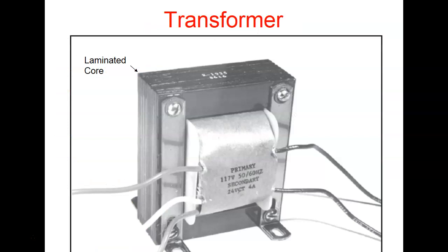So this is a transformer. In most electronic transformers, industrial transformers, especially small ones, the actual wires are going to be inside some type of plastic enclosure. I showed y'all magnetic wire last class, right? Very, very thin insulation. And if you accidentally nick that stuff, then what would happen? Now you're going to short out some of your windings, and you'll change the ratio of your voltages.